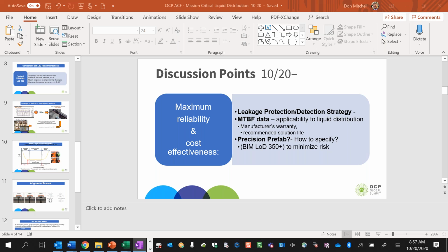Yeah, Don, this is Patrick Gingrosso. One of the questions was around just along this lines of 3 times system pressure. I think it's also good to understand what the system pressure actually is, low pressure versus a high pressure system. And, what does a leak look like in the system when you do have one, or if you ever get one? Yeah, the 3 times. So the water systems on the coil side, on the work side in the data center, we were probably running about 75 PSI, but they were designed to 125. So we were testing between 300 and 400 PSI on that work.